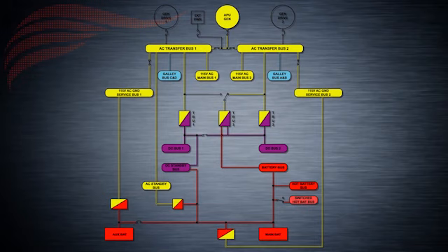For the most part, we've already talked about the standby system components. However, in order to summarize, they are the following: AC standby bus, DC standby bus, main battery, auxiliary battery, battery bus, hot battery bus, switched hot battery bus, and static inverters, which switch DC to AC power.